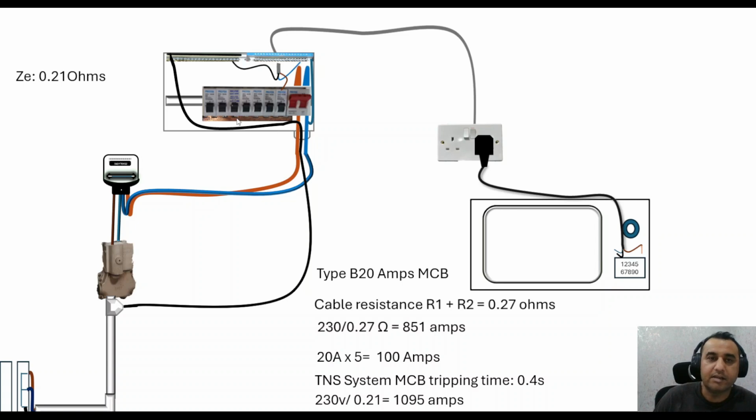Now, external system, we're taking a reading from the distributor earthing arrangement. We need to take the cable out. Sometimes you can put your meter's 3 leads, one on the line, one on the neutral, and one crocodile clip on your earthing terminal, sorry, your main earth cable disconnected from the earthing terminal.